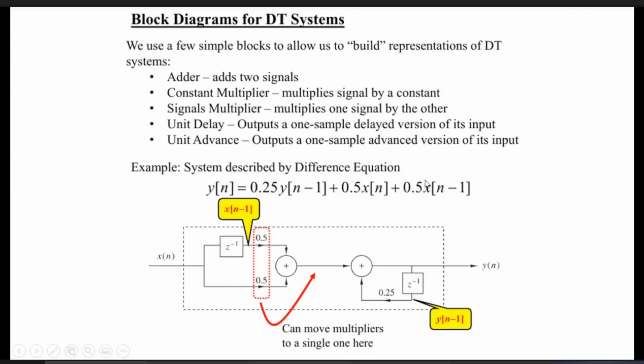We will explain later why it is Z inverse; when you put the stage Z inverse, some delay occurs, a delay by 1 unit of sample. So x[n] is your input. After passing through it, it becomes x[n-1], with scaling of 0.5. Then they are added, so it becomes 0.5 x[n] plus 0.5 x[n-1].